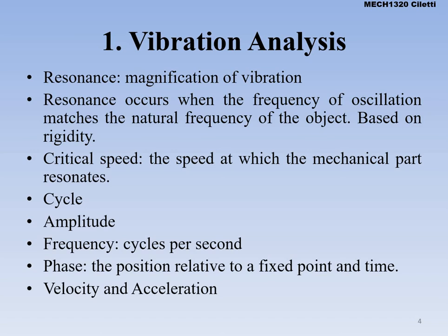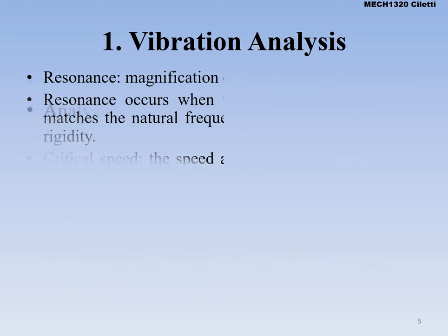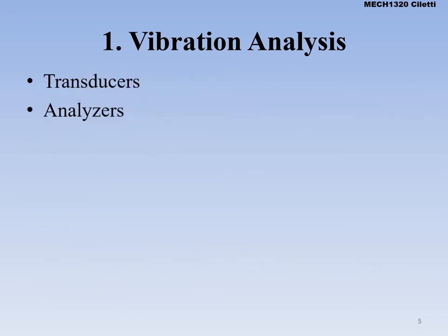And we have a bunch of different sensors and equipment that are going to constantly give us feedback in a system so that we can monitor that. You're not standing there doing it, okay? But we use transducers and analyzers. Essentially, what a transducer is doing is taking whatever we're analyzing and turning it into an electrical signal, okay? So whatever we're using to read the vibration of the motion, we're converting that into an electrical signal so that it turns it into like a sinusoidal wave or something.